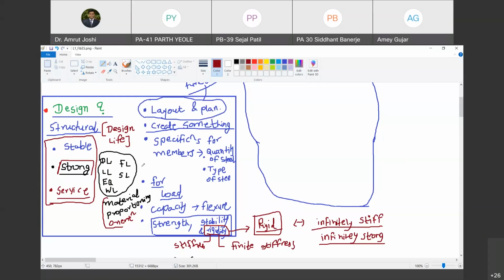Yes, sir. When a train passes over it, the sleepers are stressed. When the train goes, the sleepers are unstressed. So in comparison with other structures, it is subjected to repeated cycles of load each day. Do you agree? Yes, sir. Fatigue is degradation of strength and stiffness on account of repeated load cycles. After a certain number of train passages, you need to replace these sleepers. Why? Because they would have reached their fatigue life.